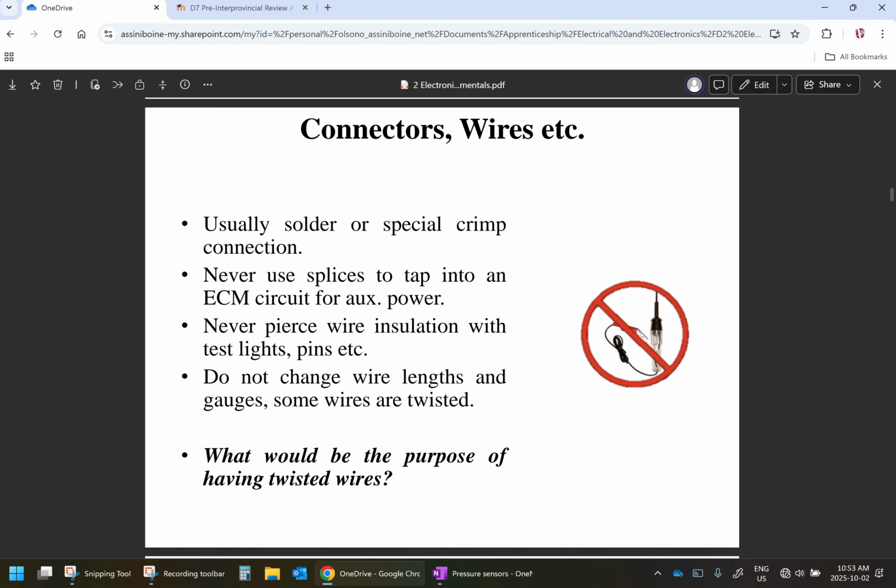So if you go ahead and make a solder connection at that same point where that break happened, you're creating a big hard part in the wire where it wasn't flexible enough in the first place. Okay? And it even gets worse because if you strip off the wire, twist them together, solder and heat shrink, and then you feed 6 or 8 inches of solder into that connection, it wicks way up underneath whatever insulation was still there. Now you've got a longer part of that wire that's going to be hard and susceptible to breakage again.